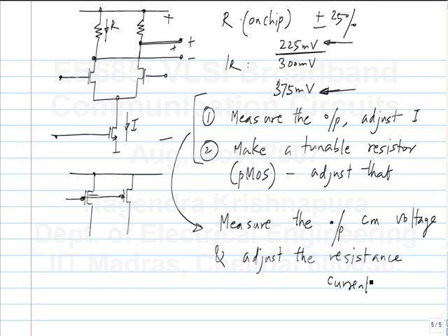So what do you do? You are measuring the common mode in a different place, right? Is that what you want to do, or do you want to sense the common mode of this flip flop? Essentially you are exploiting matching. You are saying that all PMOS resistors on the chip will have the same value. So he is saying instead of trying to muck around with the outputs here, you have a dummy where, let's say, I by 2 has to flow through this.